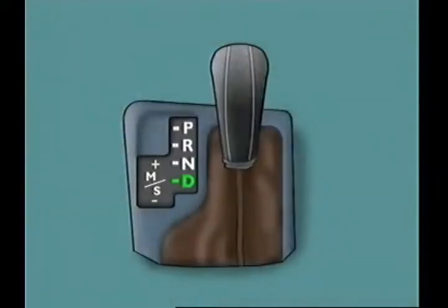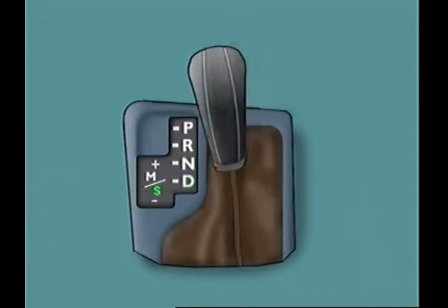Despite the benefits of adaptive control, a particular ratio can still be selected manually. In Steptronic applications, the manual program is available by moving the selector lever to the left of the D position. Automatic changes continue in a sport program until the lever is operated in a one-touch movement towards the manual mode. Forward movement changes the transmission to a higher gear. Backward movement to a lower gear.